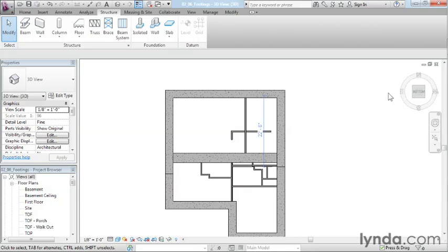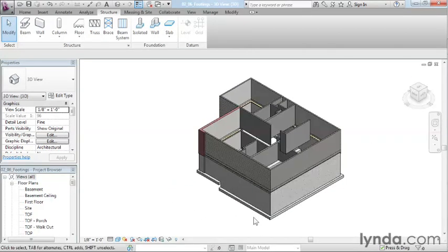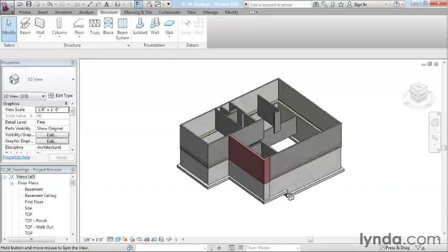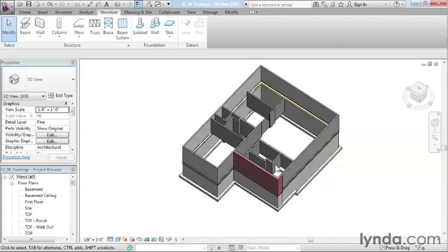Whenever you're designing a house, you always have to remember to be able to model these footings in. It's very tempting to just draw these walls around the perimeter and not put the footings in, but it's not really an accurate representation of how the house needs to be built. And when you consider this only took us a couple of minutes to place these in, it's not really worth the effort of not placing them in when you can have an actual accurate model by using your foundation and wall tools to create the footings around the perimeter and interior of your buildings.